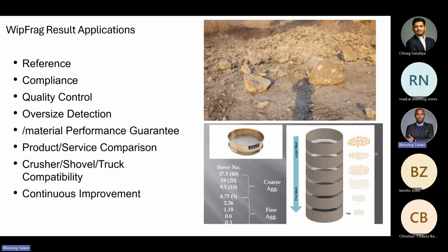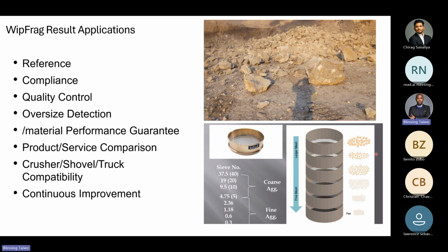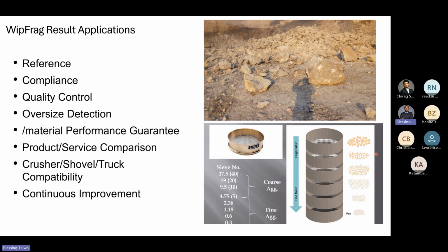Also, you want to check your blasting to make sure that you control the quality of the material coming from the blast. You can't imagine producing material that would give the loader issues during loading operation, or that will not be able to go through the primary crusher. So the better you blast your material, the better the downstream operation will flow.